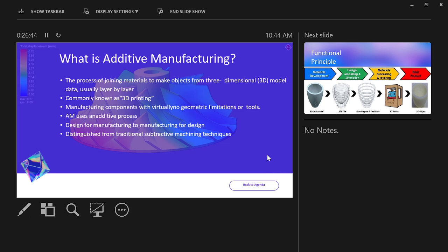Okay, so you can achieve a softer one in a single print. So there is no assembly required in this case. But here, if you want this type of parts, then it is not possible. In this case, you have to do separate printing, detail printing, and then you have to assemble that part. Then only you can achieve that. And the complexity you can't achieve or match with polyjet. So every technology has its own benefits and limitations.